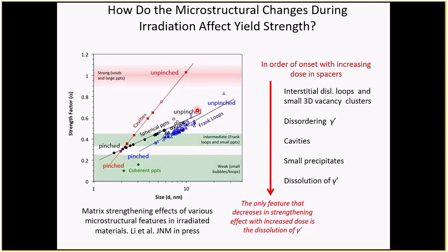At that point, the strength would go up to a certain point and then come down, because this would correspond with an aging, also the spacing of the precipitates. In this study, I'm pretty sure this is simply the size factor, irrespective of any spacing between the precipitates. So it's only the size factor that matters, for different types of defect.